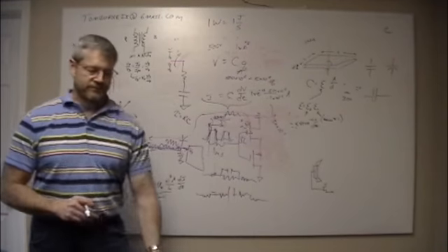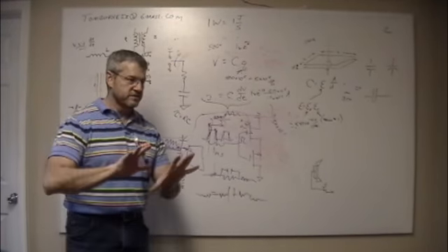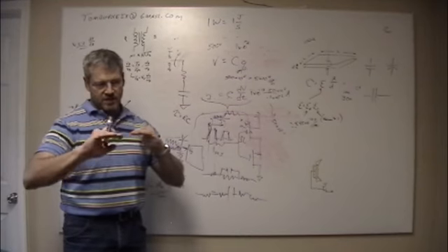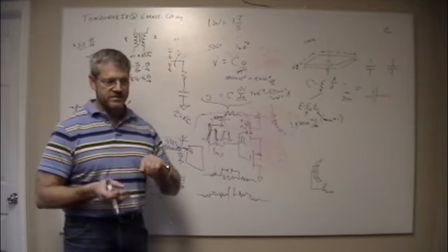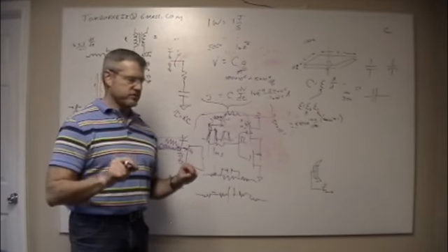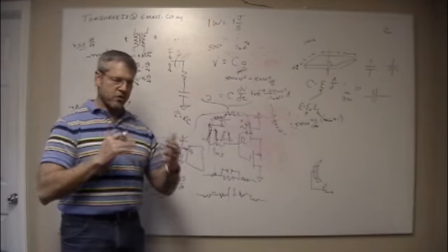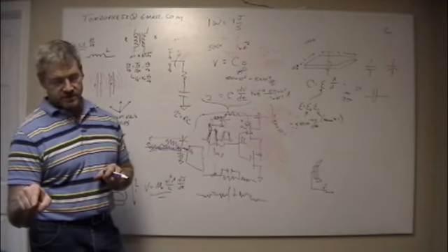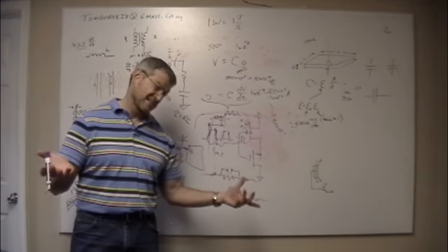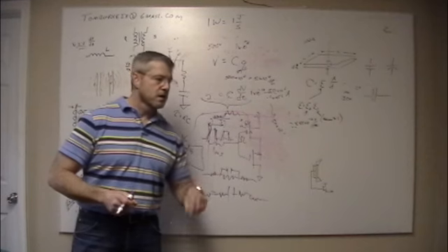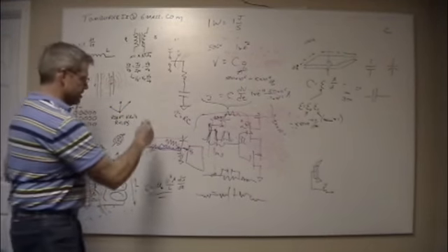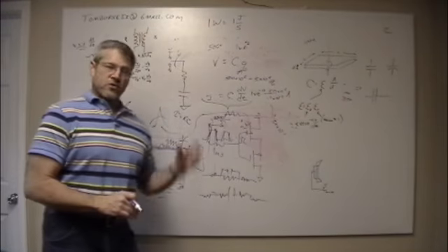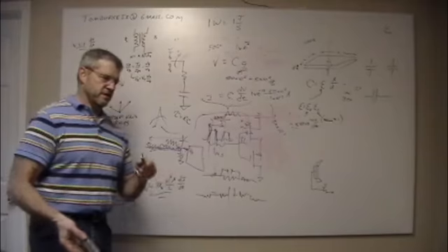So to do it right, you need to take a look at what your topology is. Capacitors need to be as close to that pin as you can possibly get them. But you want to say, I know I'm using a plane like this, so there's this parasitic capacitance and these parasitic inductances, and you want to be smart about how you choose them, because there are different styles of capacitors that have their own properties. So you want to use a 10 microfarad tantalum, a 0.1 microfarad ceramic, and a 1 microfarad mylar or something like that. Each has its own characteristic curves, which are different, and you want to play the game. Just throwing a big capacitor there is not always enough. It can actually do the wrong thing and hurt you.